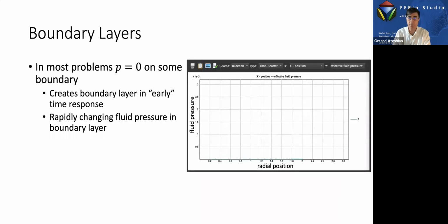It's not just that. The fluid pressurization can shift the load away from the solid when you compress it. And so the solid matrix in this case is always in tension. That's why a biological tissue like cartilage is fibrillar. Its solid matrix is made out of collagen, even though cartilage is loaded in compression most of the time. That's because it has to resist that lateral tension.